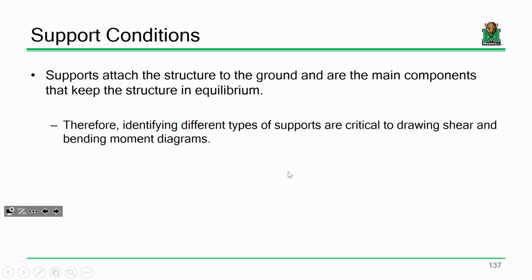It means to find the area under that curve. Well, if your shear diagram is a bunch of rectangles and triangles, do you really need to break out the calculus? No. You can calculate the area of a rectangle, just B times H. You can calculate the area of a triangle pretty straightforwardly. So we can draw shear and moment diagrams graphically. We don't really need the calculus in most cases. So we'll see how that works later on.